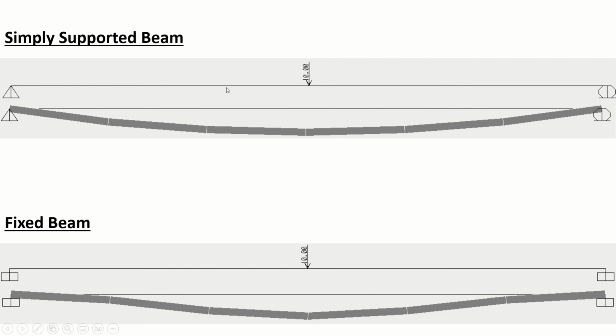Now here is another example, the cantilever beam. You can see that the beam is fixed at this side and it is free on the other side. There is no other support, and a same point load, and please keep in mind that I have kept the length the same. The same length has been subjected to different boundary conditions. So this load is applied again at the middle, and you can see that because of this fixed support the beam is initially horizontal and then it gets deflected, right? And after this point, since there is no load, it goes straight.